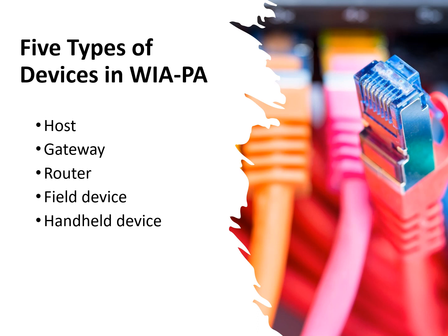The WIA PA standard defines 5 types of devices: a host that acts as the main interface to process operators, a gateway that provides the connectivity between the control network and the wireless network, a router that is responsible for the efficient and effective routing of network packets, a field device that acts as the main process enabler, and a handheld device, the portable wireless instrument.